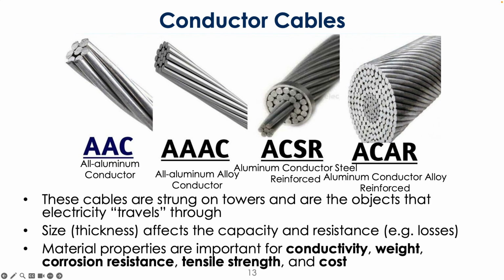Aluminum is typically a really good conductor, right? And so you want good conductors because they have low resistance, which means that you have lower power loss. Even though we primarily think reducing current is going to do the best, you still want your resistance to be as low as possible.